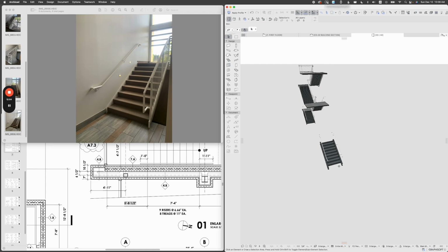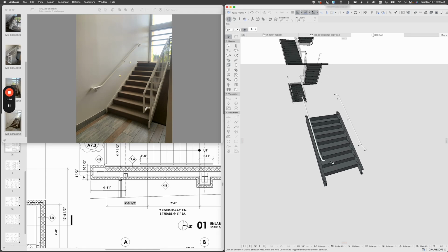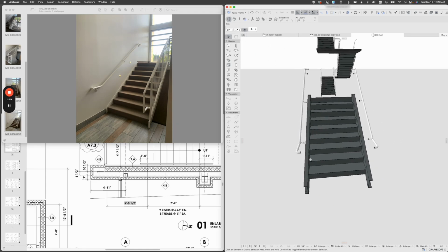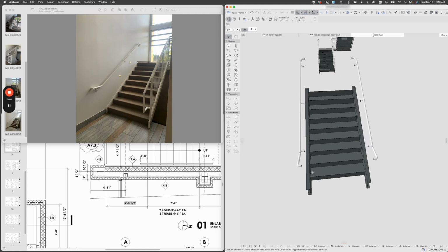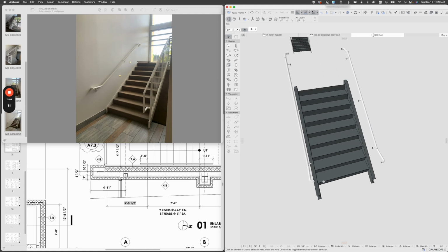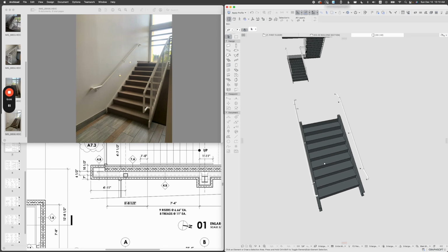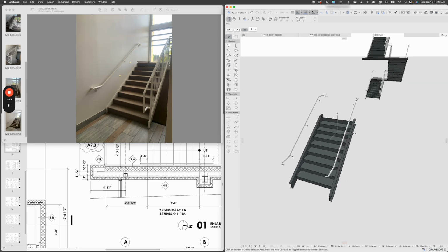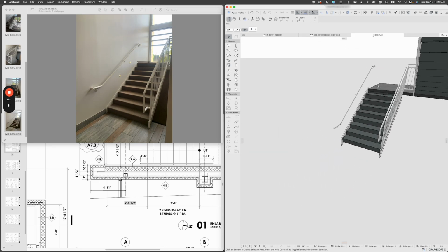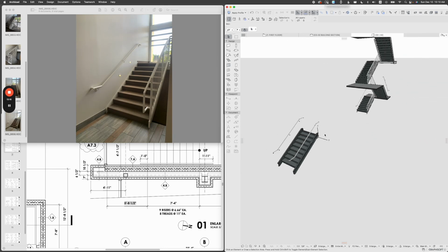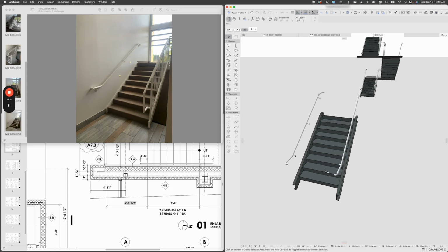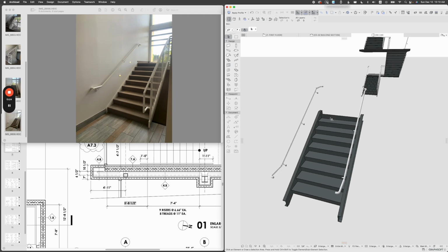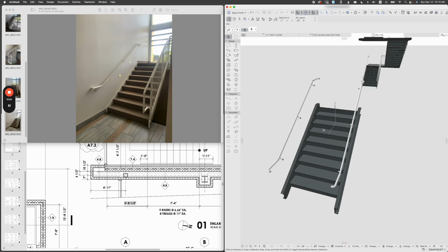So it built this stair, which was again a default from ArchiCAD, and it also built these handrails, which are rotated in the wrong direction. Why they're rotated in the wrong direction is because the last handrail I was modeling for these stairs, I was using this profile, and somehow it just remembered that last one, and it was probably rotated to a different side, because there are different settings for the left and right, and somehow it just messes up. But it's not a problem.